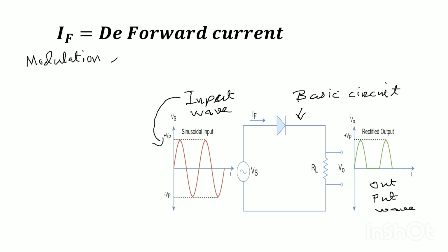Note, it is common practice to use V instead of E in denoting voltage for diode and transistor characteristics. This will be adhered to in describing the characteristics of semiconductor devices. When the diode is reverse biased, this current is called IR, and it is 0 regardless of the value of VR.